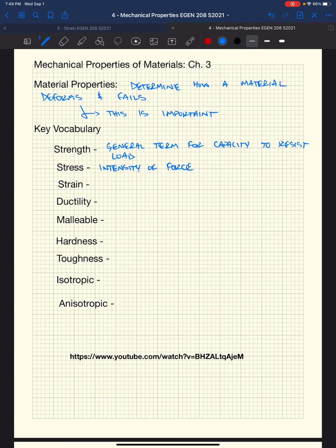We have shear stress, we have normal stress, and we could have a combination of the two. Strain is the intensity of deformation. Again, we have normal strain, we have shear strain, and we could have both, a combination of them on a given plane or face that might not be acting strictly parallel or normal to our shear stress or our normal stress.